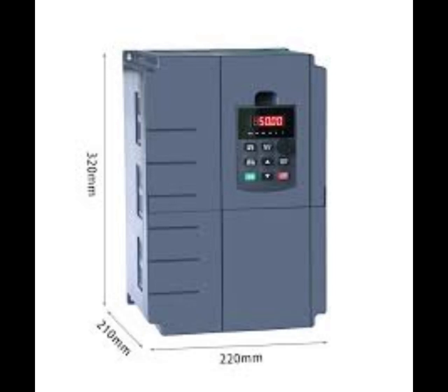Current limiting. This controls the maximum amount of current the drive is allowed to deliver to the motor. Volts per hertz. This sets the ratio by which the voltage increases as frequency increases or decreases as frequency decreases. Maximum hertz. This controls the maximum speed of the motor. Minimum hertz. This sets the minimum speed the motor is allowed to run.